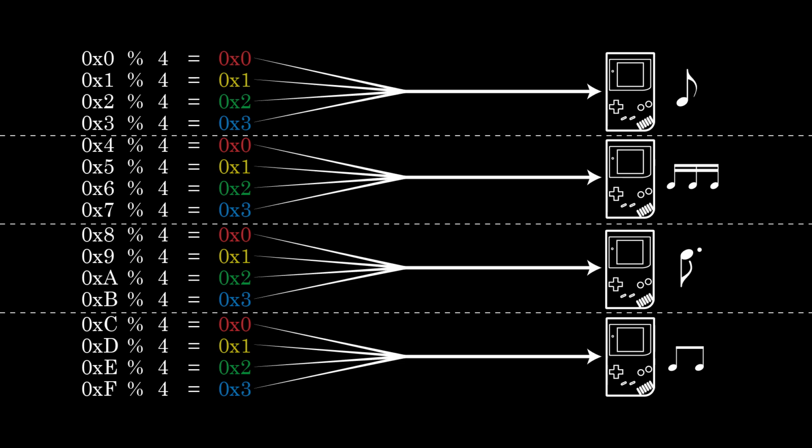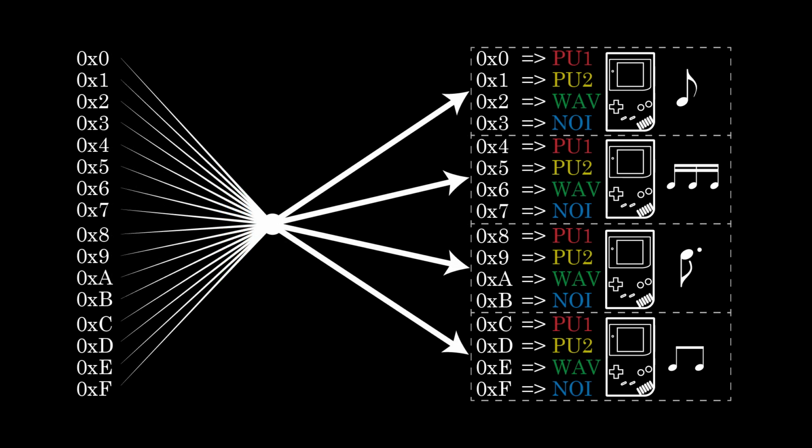the multi-interface link system. This new methodology was given the name Single Interface Link, and as you might imagine, it does away with the isolated electrical signals and allows each Game Boy to receive its data from a single interface connection. However, with each Game Boy receiving the data of all 16 channels within a MIDI song, I obviously needed to introduce a way for the Game Boy to autonomously decide if a received signal is to be processed by one of its sound generators or not.